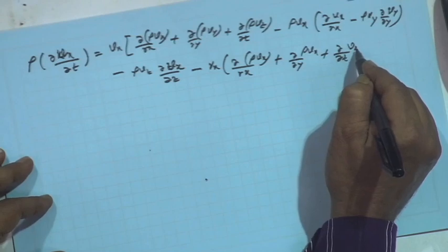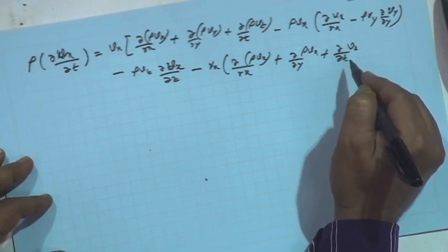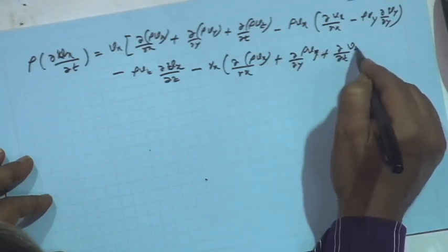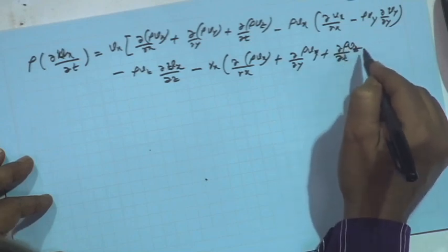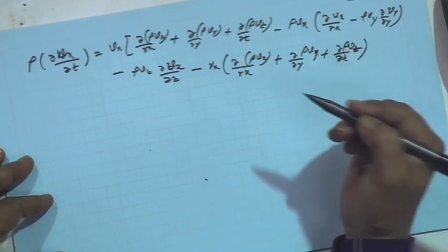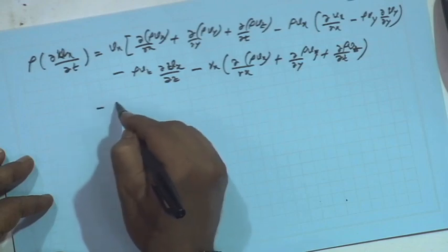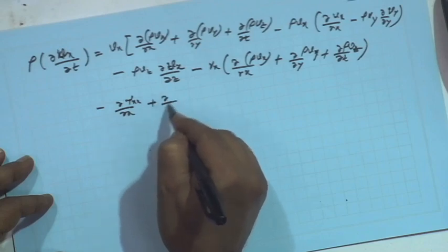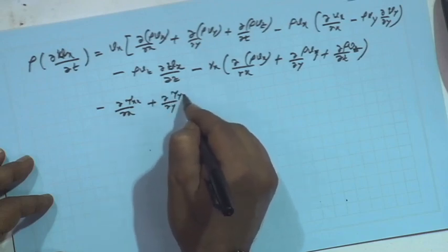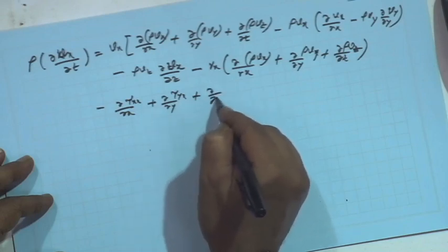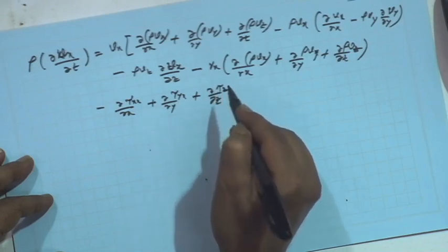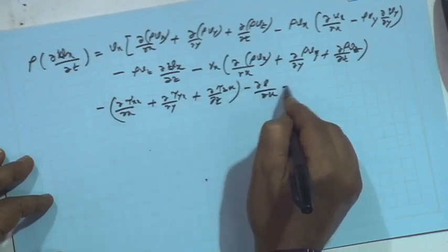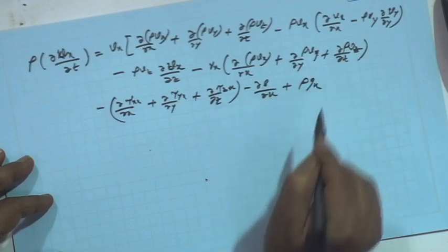So, this also will be rho Vx. So, we can write, so del rho Vx del x, oh sorry, this is y and this is z, right, rho Vz. This if we write, then minus del x of tau xx plus del y of tau yx plus del z of tau zx, right. So, this minus del p del x plus rho gx, right.